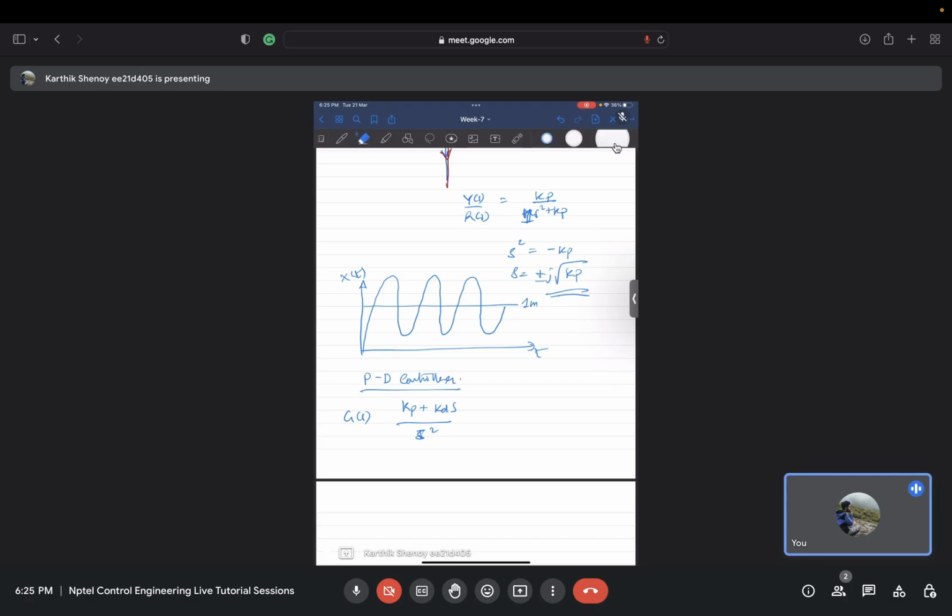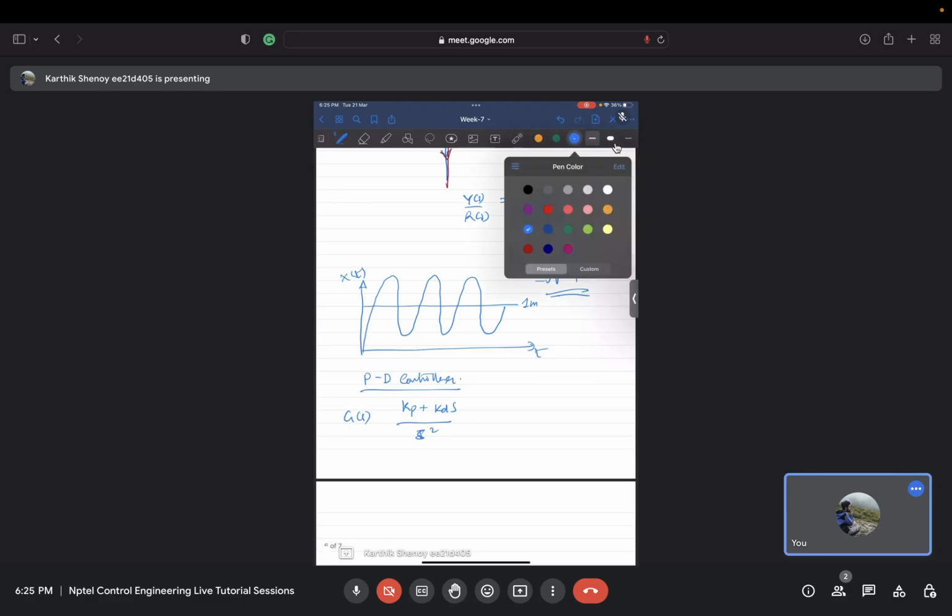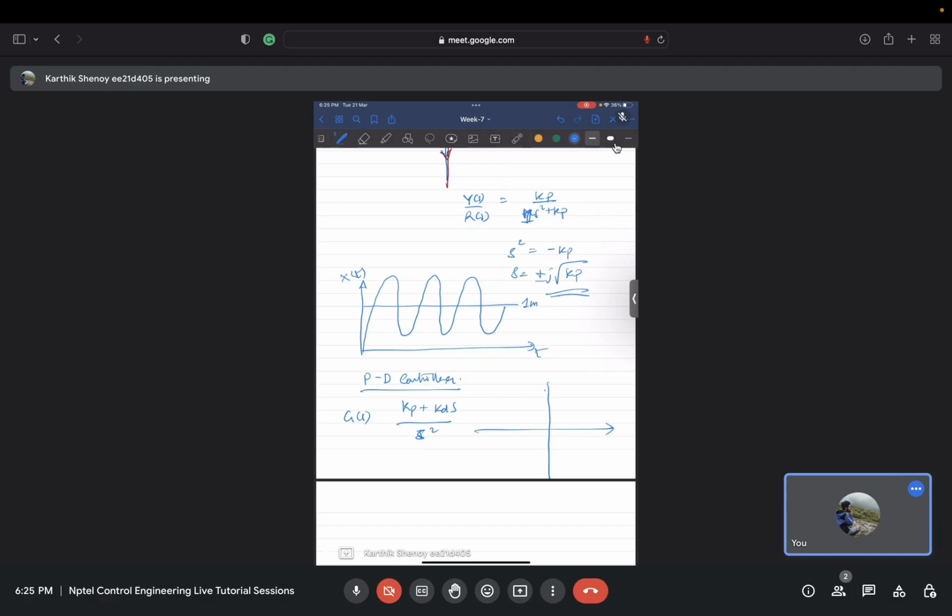So it added a 0 to it, correct? What does a 0 do? Shift my root locus to the left. So I will just draw that. Now I can change the location of 0 by changing Kp and Kd, okay. So my poles were here, I added a 0 here. What will it do? So you will see something like this.